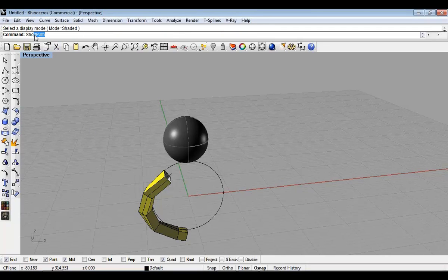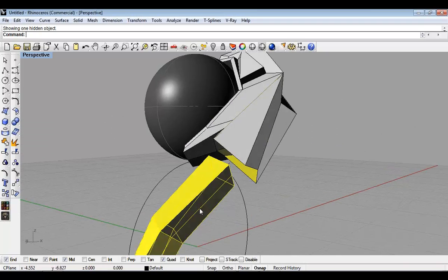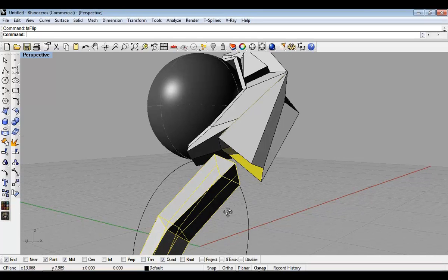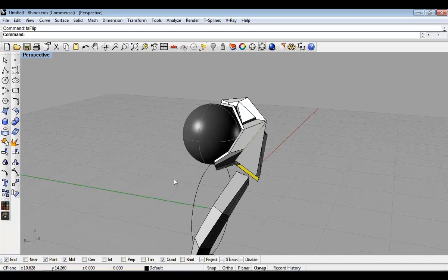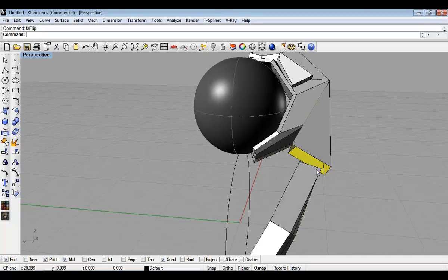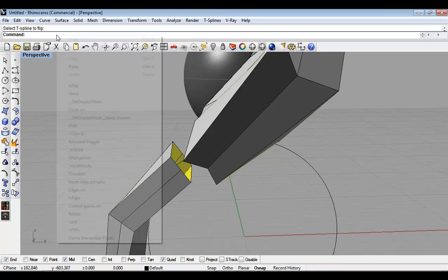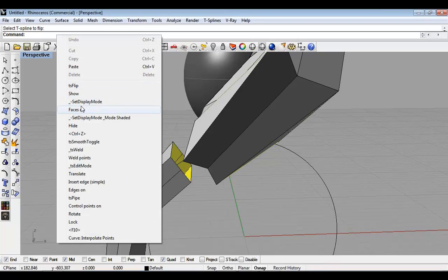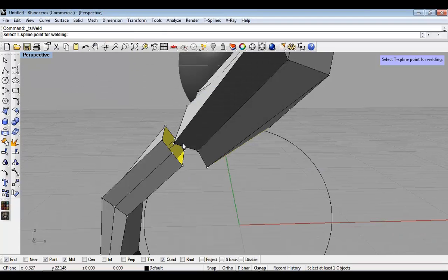In all seriousness, pulling out errors like that is kind of my agenda for today, because trying to weld something that has a face on it is not entirely obvious that it wouldn't work. So glad it was Chris that figured that out. Because I work in ghosted mode, it can be difficult to see what you're doing. What am I doing? TS weld. Alright, so now when I work my way around, it should be good.